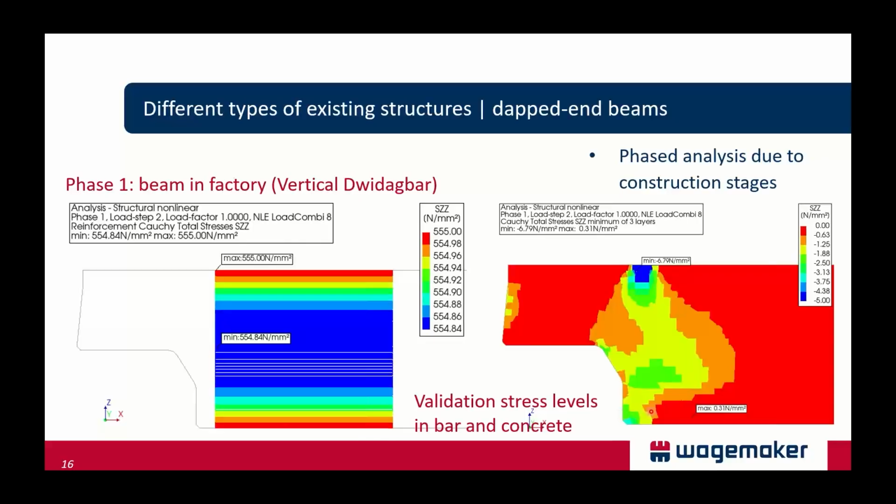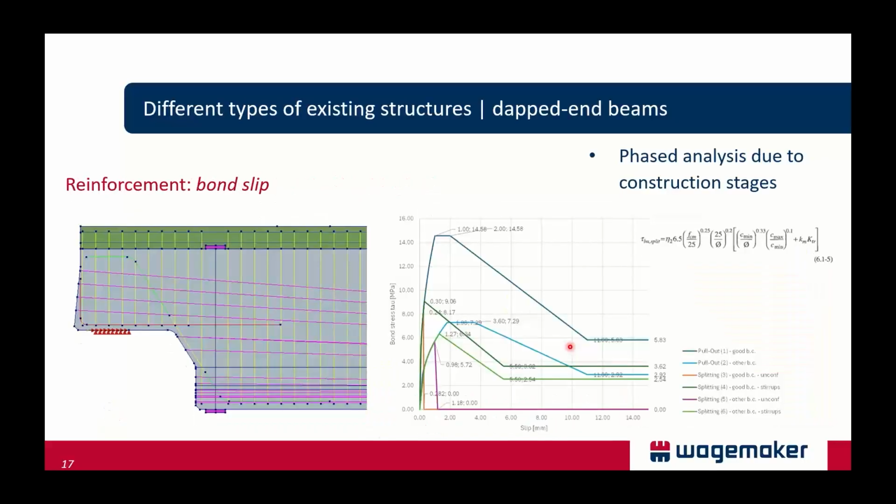But remember, this was a T-shaped girder with a bottom flange. So obviously we should find a pressure that is higher on the top side than it is on the bottom side. So this looks satisfactory. And the reinforcement was modeled as embedded, but also as bond slip relations.